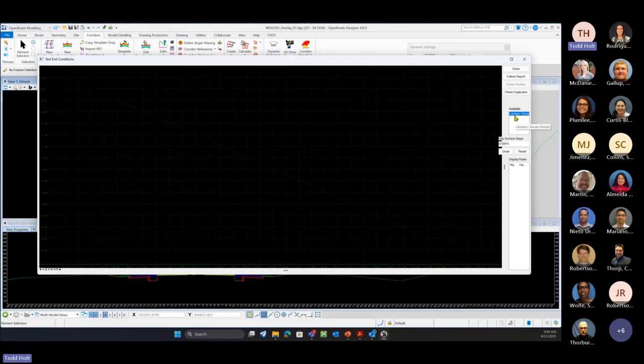And we're going to mimic drawing this active terrain or existing terrain. And we can set a different slope for that. So our end condition is looking for our terrain model or an active terrain. We can set the slope for it. We're just going to leave it at 0. We can put -2, -3, whatever slope that we want. And we're going to draw that end condition.